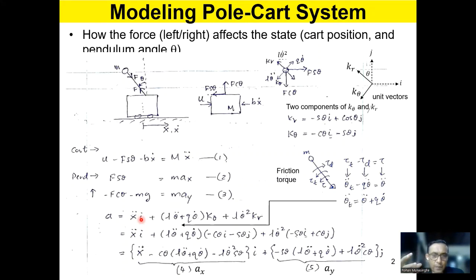So therefore, whatever acceleration is there on the cart is applicable to the pendulum as well. So the pendulum gets x double dot i in the horizontal direction, this linear acceleration. Okay, and in addition to that, it gets L theta double dot plus q theta dot coming over here, right? The total acceleration, theta double dot plus q theta dot, these two components together,